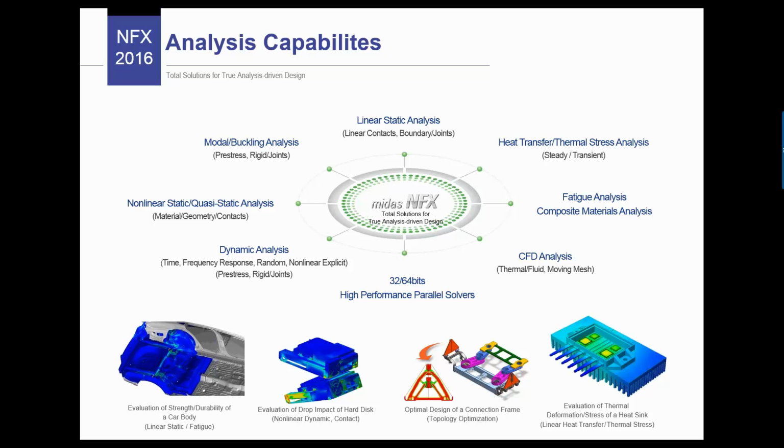Now let's talk about the features of the solver. Midas NFX, as I was telling, has a lot of different types of analysis available. It's not only linear static analysis, which is the most basic, and if you're checking a design you will probably only use linear static analysis. This is the most common analysis used, but you have to know that there are a lot of hypotheses in linear static. First it is linear and secondly it is static.